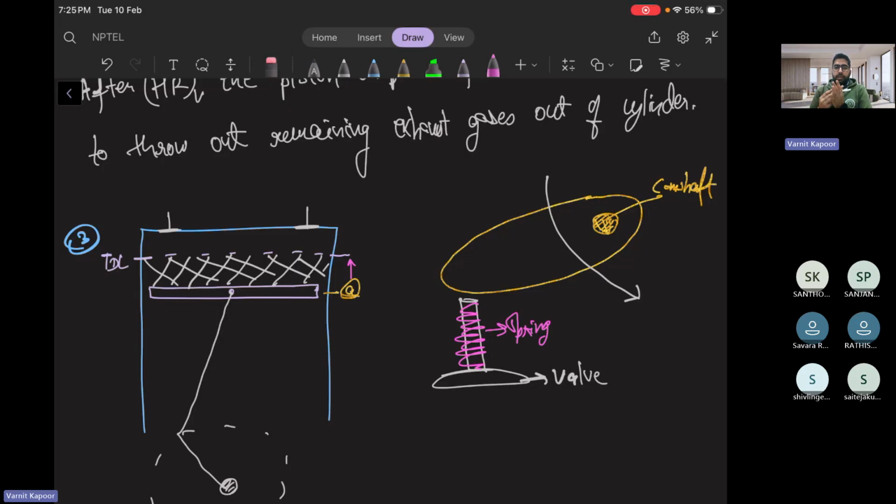So this is moving actually. We have this exhaust valve and it is moving. When it is pushing down, the valve gets opened inside the cylinder, but only for a short duration of time. So the time for opening is less, then the spring will pull it back and the valve will be closed again. The time for closing will last until this tip of the shaft matches with this tip, or some region of the tip.